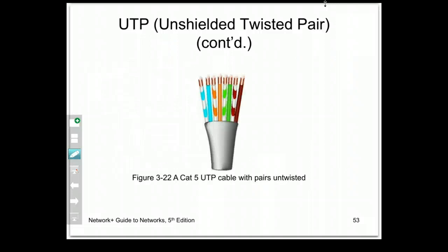And we're going to end on this slide because you'll be beginning on this slide next week. You have your different color codings on Cat5. And this is unshielded twisted pair. The trick is this. Let me show you. So you've got brown, stripe brown, green, stripe green, orange, stripe orange, blue, stripe blue.